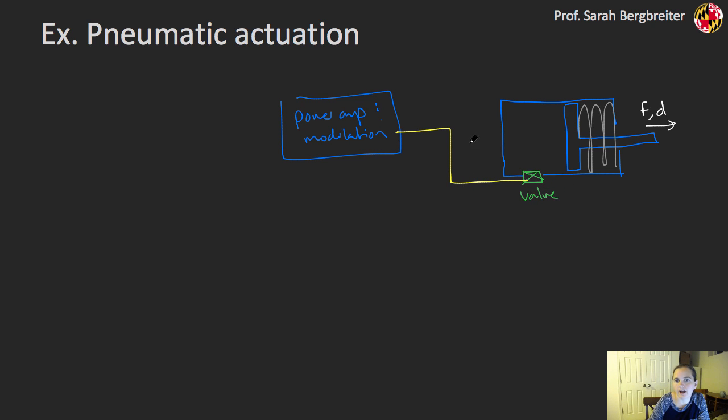And by controlling that valve, along with some other reservoir of pressure, so I might have some kind of compressor up here that I can send air into that valve with. So this is kind of my power supply equivalent in my pneumatic system. Right? By controlling that valve, I can control the flow of air into this cylinder here. And then, of course, the idea is that ultimately something like your Arduino or some other microcontroller could be used to switch these valves. So maybe there's some kind of solenoid, which are electromagnetic actuators in their own right,